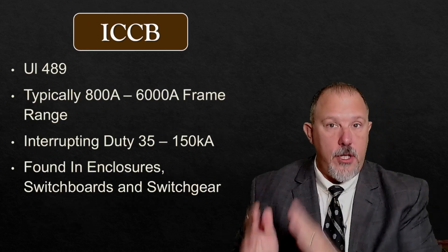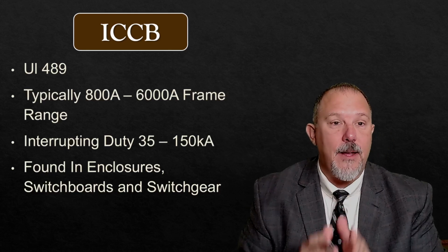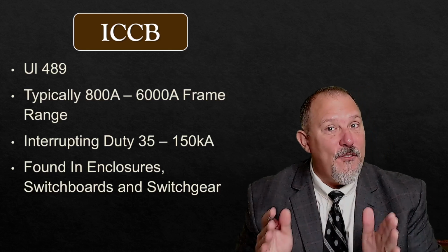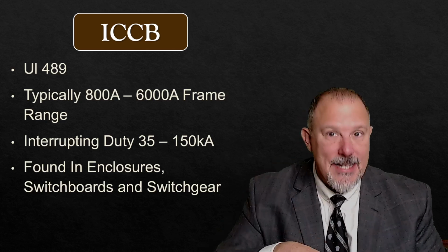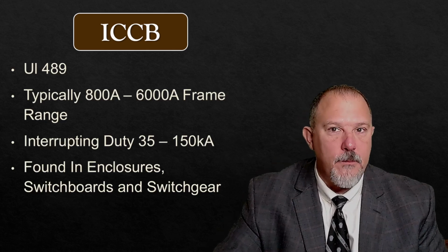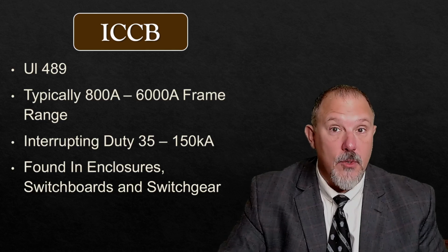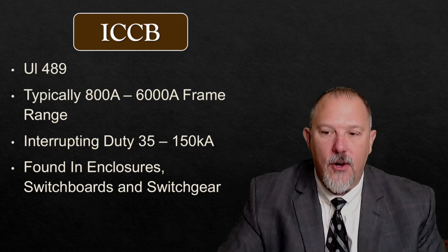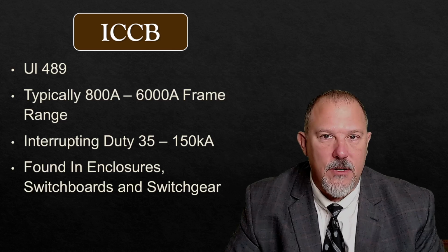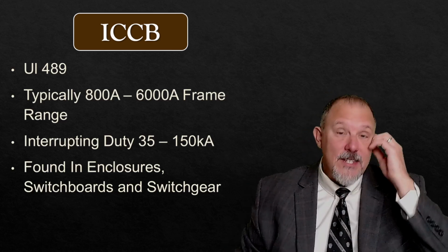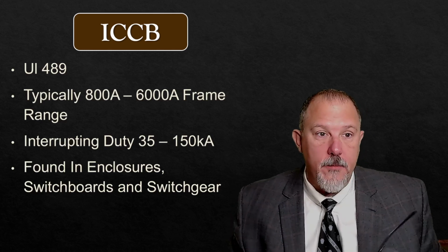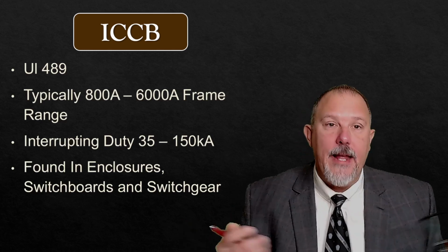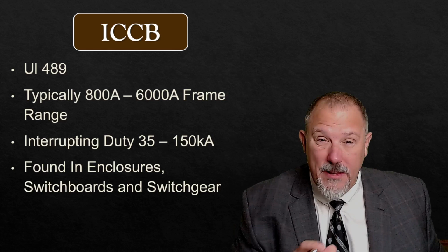Now, the other 2, insulated case. An insulated case circuit breaker is a UL489 device. A lot of people don't understand that. Technically, an insulated case circuit breaker is a molded case circuit breaker. Why do we call it an insulated case circuit breaker? That's a good question. It's a marketing thing. It's a marketing term. It has nothing to do with it. And when I say a marketing thing, I don't mean that in a bad way.